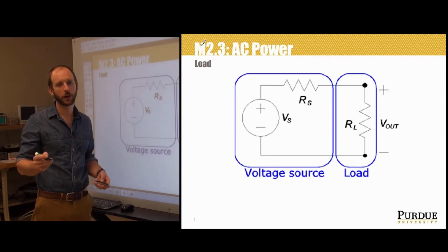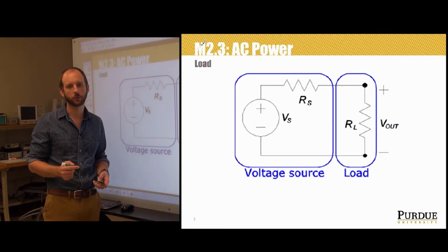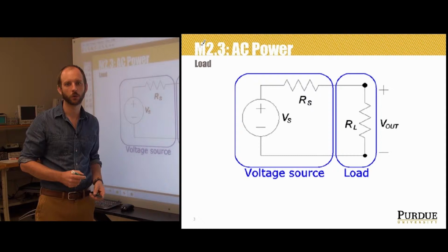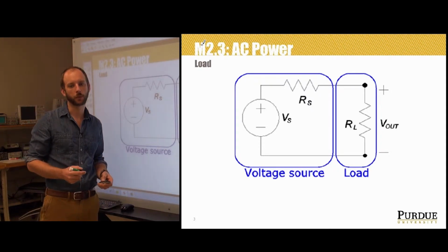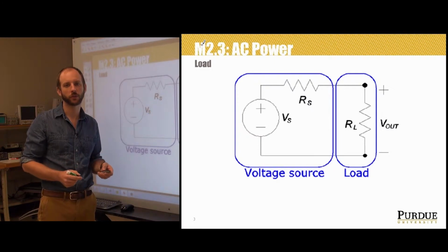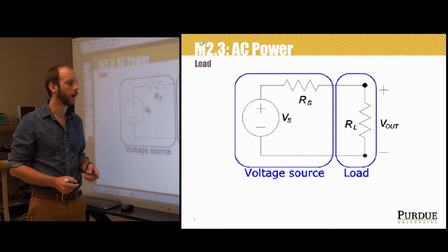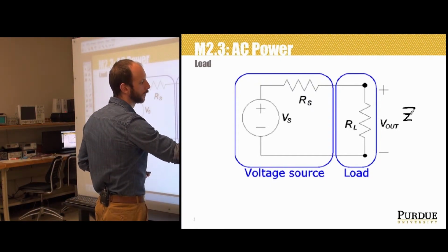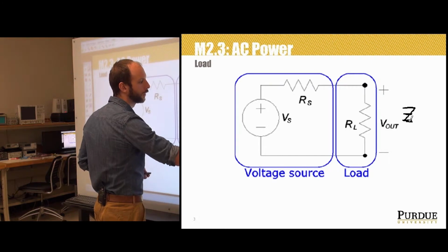If we talk broadly about loads, we can say that electrical loads have 2 main characteristics. First is the resistance, as we're already familiar with. The second is a property called reactance. Combined, resistance and reactive effects are called the impedance of a device, often symbolized by the capital letter Z, more specifically a bold Z.